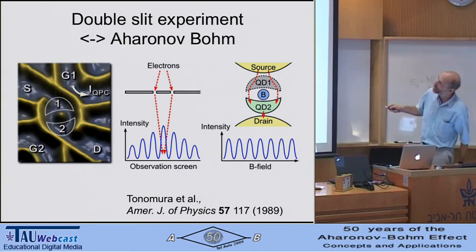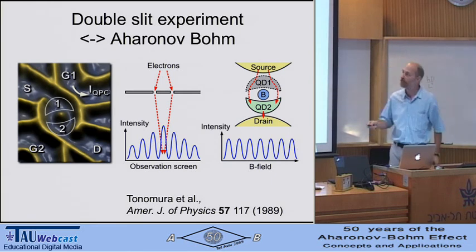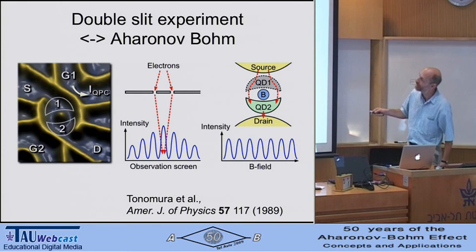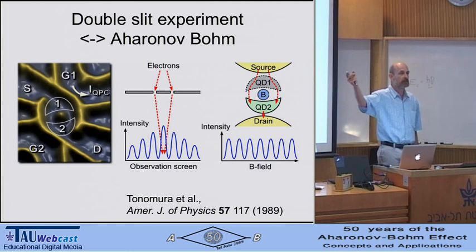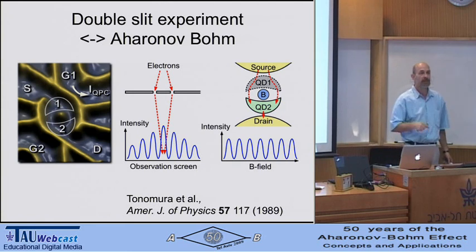Now there's a little gadget up here, and this is our detector. This detector is simply a tunnel barrier, and the conductance of this tunnel barrier is coupled to its environment by electrostatic means. So each time you load an additional electron into your system here, there's capacitive crosstalk to the other side, which leads to a conductance change of our detector. And if we monitor this conductance change as a function of time, we can really probe how the electrons go through the entire structure as a function of time.